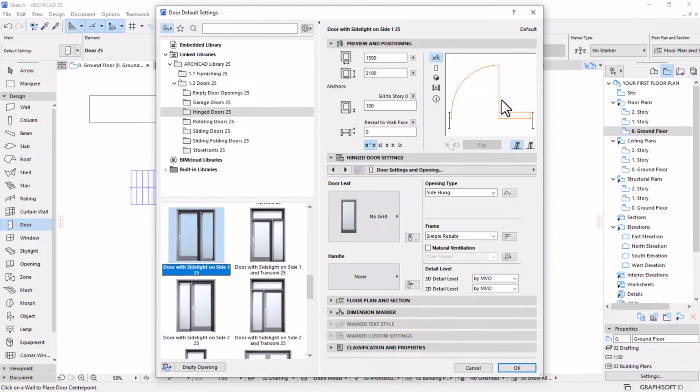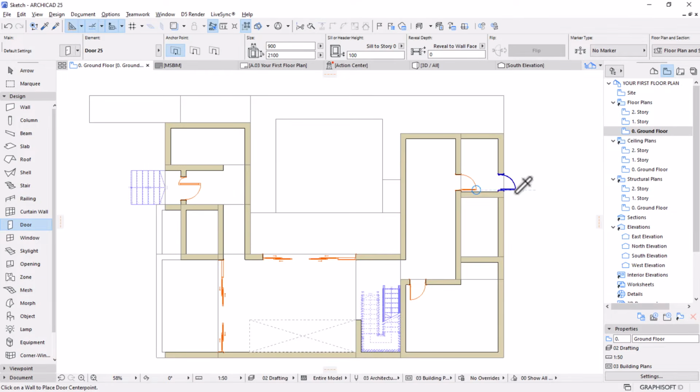you see now it loses the settings that we've set, the 2D detail level. So you can imagine when you are setting most of the parameters of your door, and then you keep on coming back and redoing it, it's going to take a lot of time for you. So to save settings is to pick parameters like I did of the already set door.